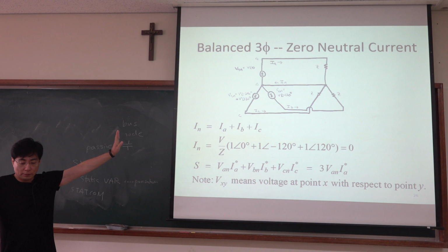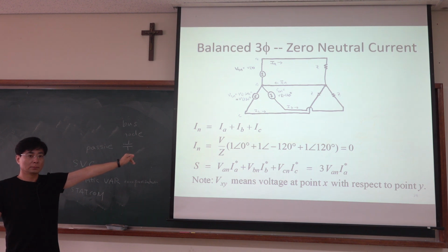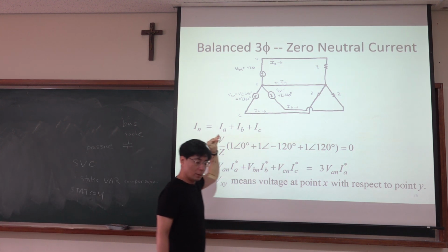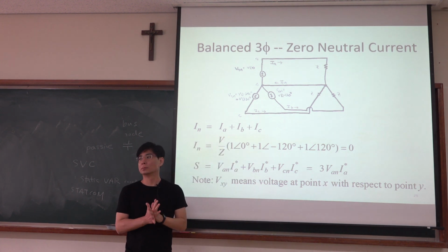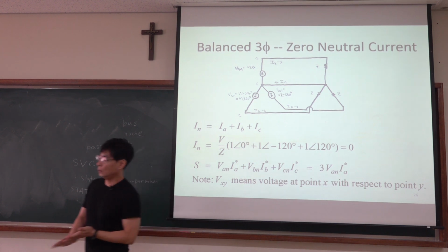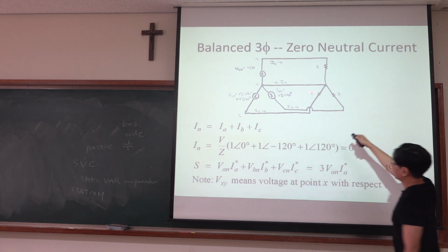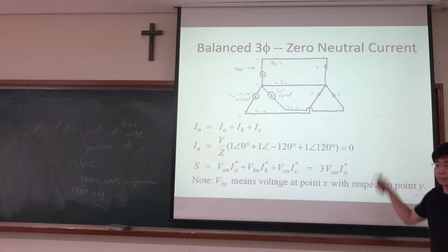Before talking about the advantages of balanced three-phase system, when can we assume a balanced three-phase system? When? And to use this balanced three-phase system, what should we do? Well, at least you need to make this load side has the same impedance, Z. They should be same, okay?